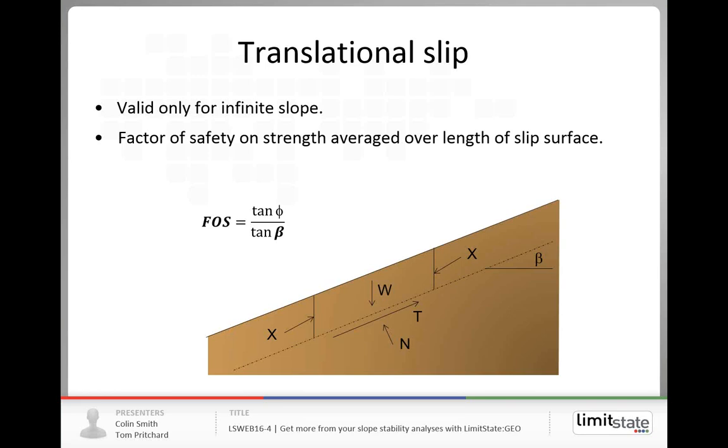If we examine standard textbooks, we'll see a number of conventional analysis methods suitable for hand-type calculations. We'll just look quickly at 3. The simplest is probably planar slip analysis, really only applicable to infinite slopes, but it's straightforward. By looking at simple equilibrium, we can determine a factor of safety, which in this case is effectively determined as a factor on soil strength.